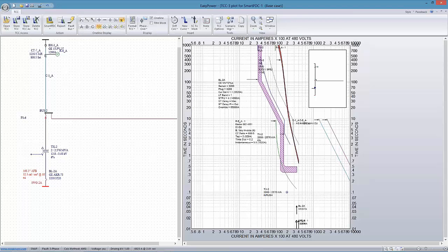Makes me think that just looking at the curves, the relay in fact is a more limiting factor. So let's see if we can try this again. It's not going to let me do it. So one way to verify that is by selecting this breaker. There it is. So by selecting the relay curve, you can see that now I'm seeing the arcing current 85% is being used for calculating the incident energy, but it's being overridden by the effects of the relay.